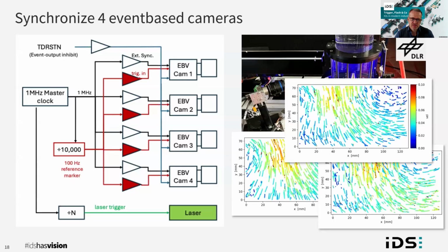The 4 event-based industrial cameras from IDS used for this purpose offer 2 particularly useful I/O interfaces. This is a trigger input that enables a unique timestamp to be placed in the data stream so that the events for 3D triangulation can be easily matched or precisely assigned to each other.